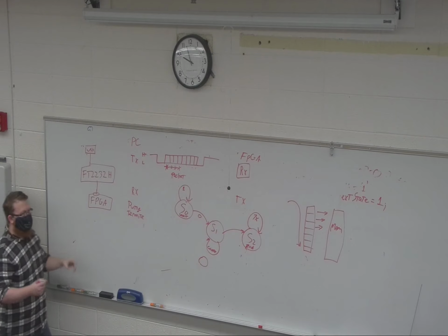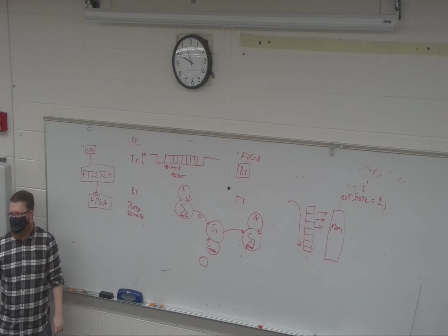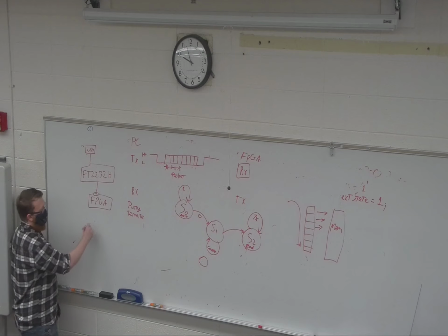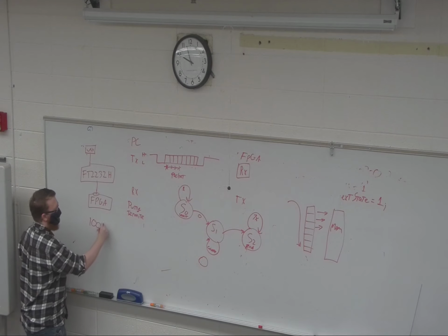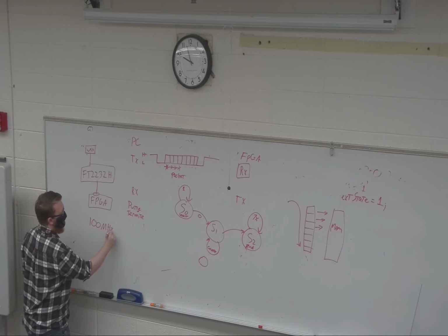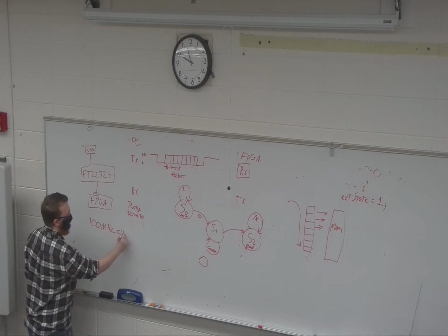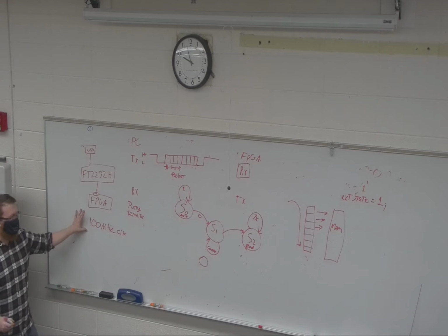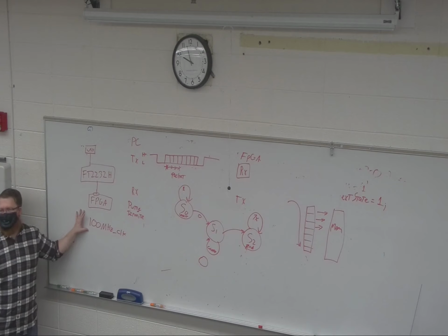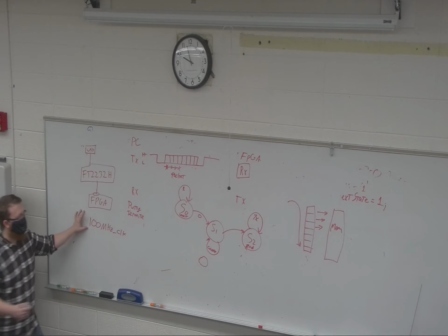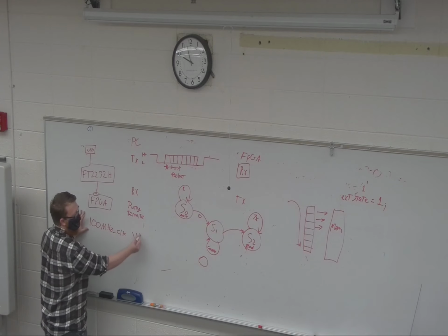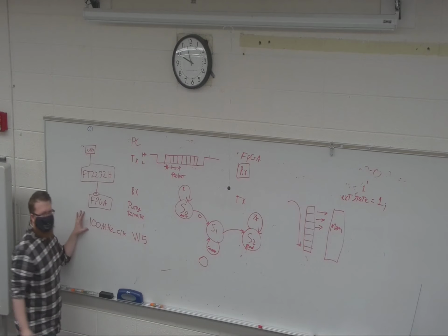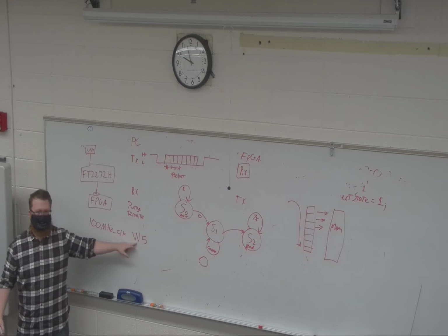So for example, if you look at the code that we used for Lab 0, it has that 100 megahertz clock, right? That's the signal they use for your clock. And then if you go and look in the .xdc, the constraints file, they link that to W5. The reason is W5 is your dedicated 100 megahertz clock pin.